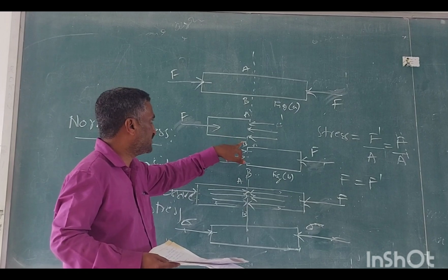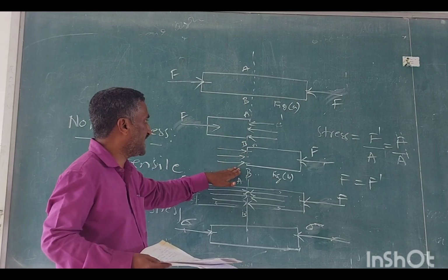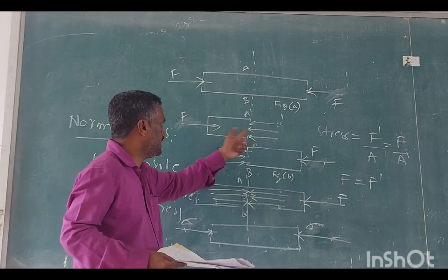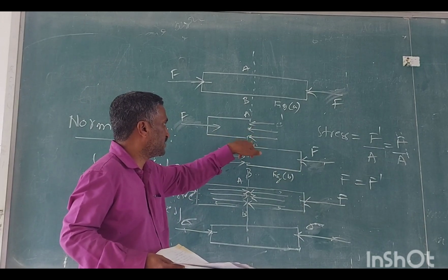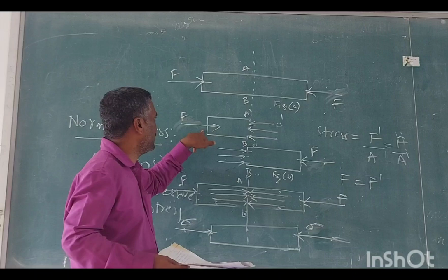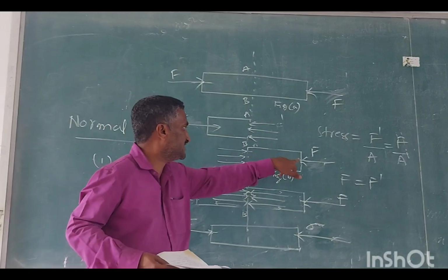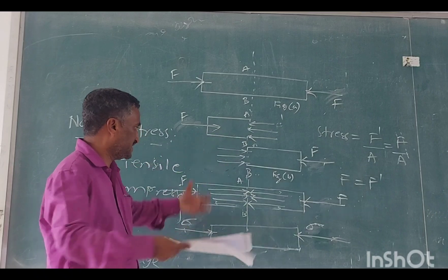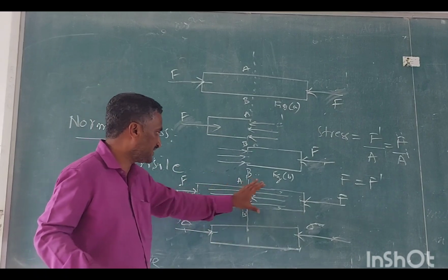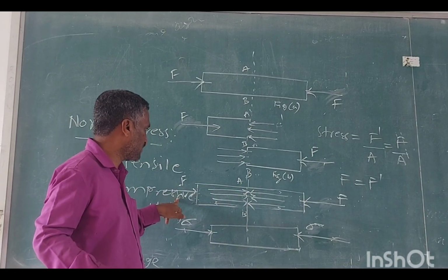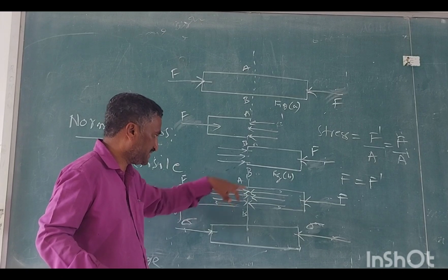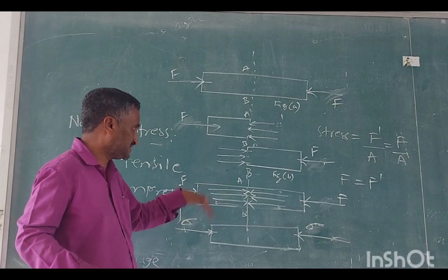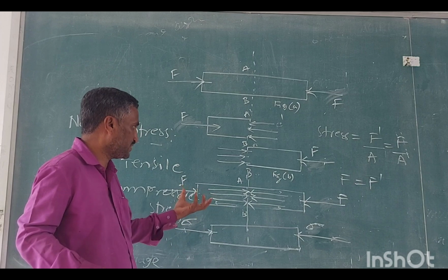So the resisting force is there. That is coming exactly opposite to the applied load. The applied load acts only like this, but the resisting force that is developed inside the material will be exactly opposite to the applied load. Now if you combine these two things in a single component, it will come like this. Again, the compression load applied as well as the resisting force set up inside the material will be exactly opposite to each other. That is called compression stress.